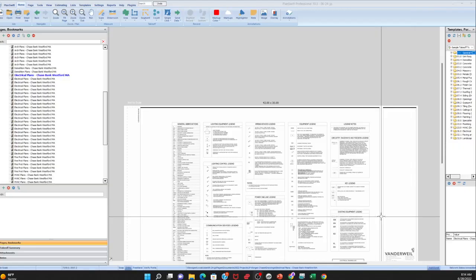Okay, and two, if it's like a Chick-fil-A I've done, where they have the loop, now we're talking about site work. The loop detectors when they drive through, well, you have to have the conduit. An underground conduit is always PVC. So we always say when we see site work, even if it's the lighting site or whatever, it's always PVC